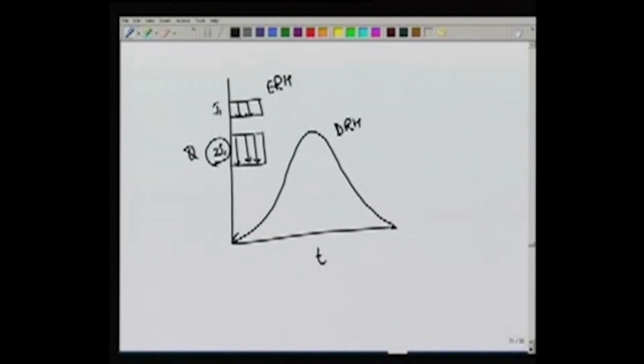So everywhere, if you take the ordinates, this ordinate will be twice this ordinate if the rainfall intensity is twice. So the principle of linearity and time invariance help us in analyzing a lot of different kinds of storm patterns in order to arrive at the corresponding DRH.